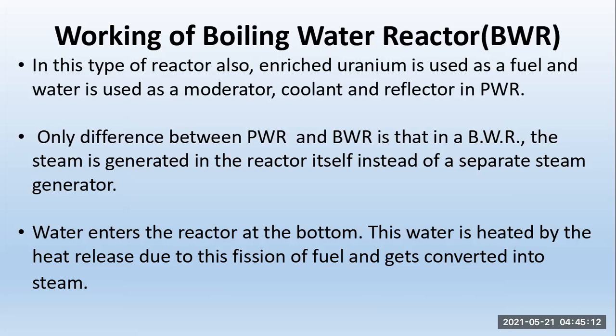The water in the primary circuit gets heated by absorbing the fission energy in the reactor core, and the same energy is given to the heat exchanger to generate the steam. The water coming out from the heat exchanger is circulated by the pump to maintain the pressure in the circuit in the range of 100 to 130 bar.